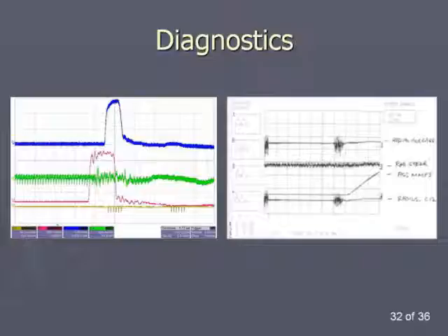And similarly, you can get all the high voltage functions. In addition to the voltage functions, those functions are the amplitude of the RF in each of the cavities. There's also an RF sweep function, which is the vector sum, right? The total amount of kick the beam gets. And that looks more like a sine wave rather than just the amplitude as a function of time. And you can measure the RF frequency with that, right? There's a frequency analyzer at MCR4. Again, non-invasive and useful.